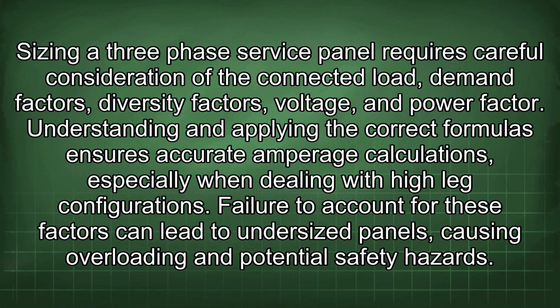Sizing a three-phase service panel requires careful consideration of the connected load, demand factors, diversity factors, voltage, and power factor. Understanding and applying the correct formulas ensures accurate amperage calculations, especially when dealing with high leg configurations. Failure to account for these factors can lead to undersized panels, causing overloading and potential safety hazards.